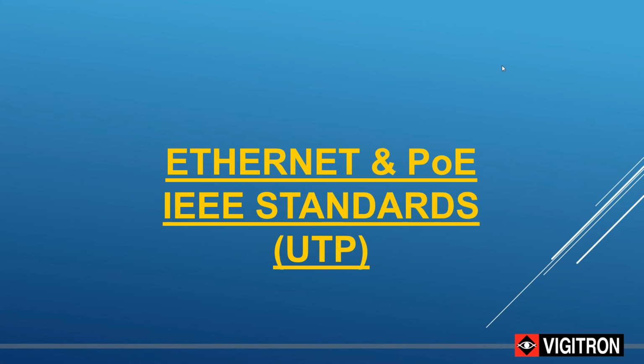There are two reasons for this. First, historically, for approximately 40 years, coax cable was the primary method for CCTV transmission. That's perhaps millions of installations with existing coax with a transmission distance of 750 feet to potentially 1,000 feet, or 2 to 3 times the distance of standard IP-PoE transmission, still in existence today.